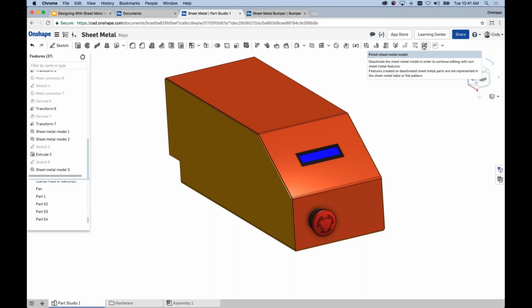Again, just keep in mind, when you do this, you're creating a sheet metal part that can unfold. But there are certain things that can't unfold. Examples would be those welded in PEM fasteners or those embossed feet. And those you would do after the sheet metal part is cut and bent, right? And those would be considered finished sheet metal features.